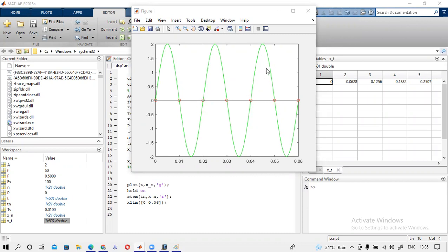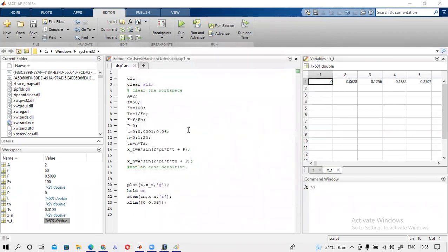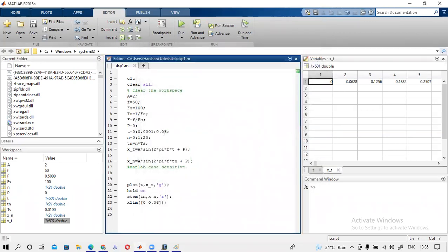If we get the double frequency, in some cases it is not possible. If you start the sample here, sometimes it is quite good, but if you take the sample here, you will get the wrong signal. Okay, so when you are doing the sampling, please select the maximum sampling rate you can. Actually, the main problem with signal processing is still the sampling.